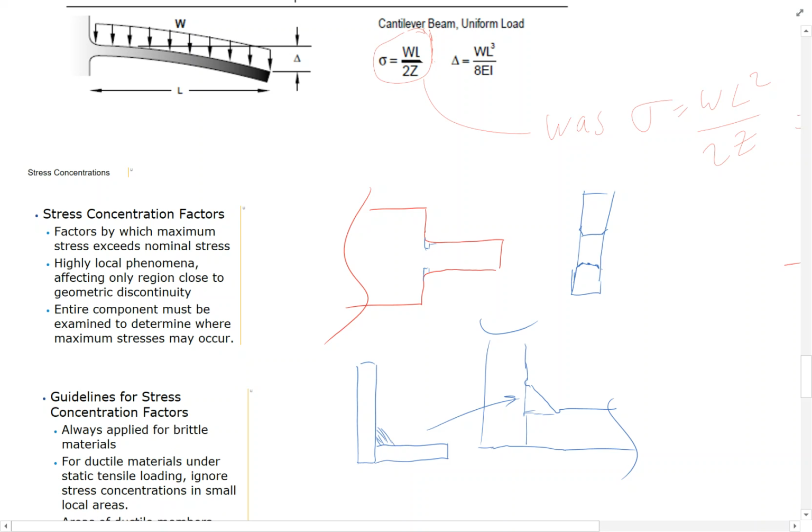Fatigue is a fascinating topic to me. If I was going to be an analysis person, that's what I would want to focus on. But typically in fatigue failures, or always really, you get an initiation point, typically a sharp corner, and a crack initiates. And then that crack grows, and then ultimately you get failure. I've got some examples when we get into that section where 70-80% of the material is no longer connected, where you'll have a shaft with a crack that extends 70% of the way through the structure, and yet it's still operating, meaning they way over designed in terms of average stress.